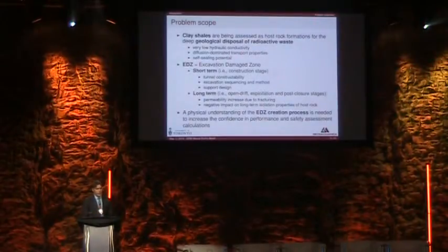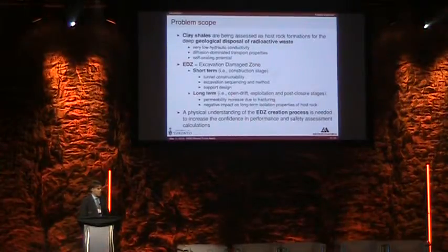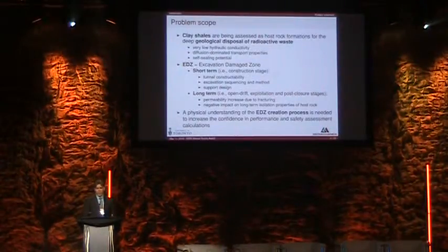However, one concern is related to the damage induced around the underground excavation, the so-called EDZ, excavation damage zone. The EDZ has implications both in the short term, when it comes to tunnel constructability, design of support, excavation sequencing and so on, but more importantly in the long term, because fracturing might be associated with an increase of permeability, and so a negative impact on the isolation property of the rock mass.